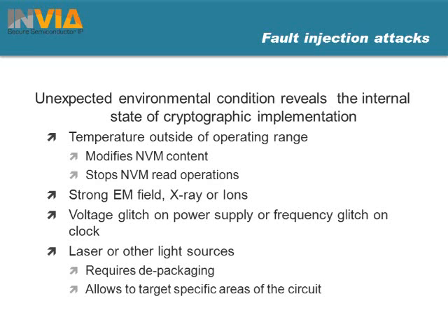But basically, the idea is if your chip is not operating in its normal condition, you can disrupt the calculation of a cryptographic algorithm. And if the calculation is disrupted, you have access to what is called a faulty result, so a result of the calculation that is not the expected result.